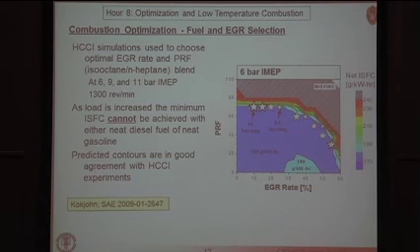So basically, you're kind of walking a tightrope here. If you go far into the blue region, you get very high pressure rise rates, which is not of interest, but relatively low fuel consumption. So you kind of want to be in this light blue region here where the stars are small. Okay, so what this shows you is that if you have diesel fuel with a PRF number of around 20, in order to be in that region, you have to run with EGR rates around 55–60%.